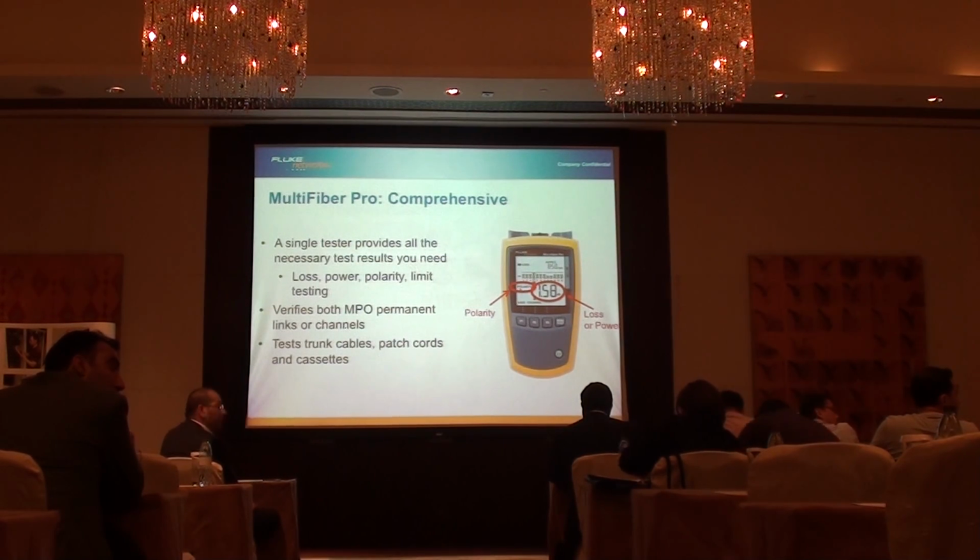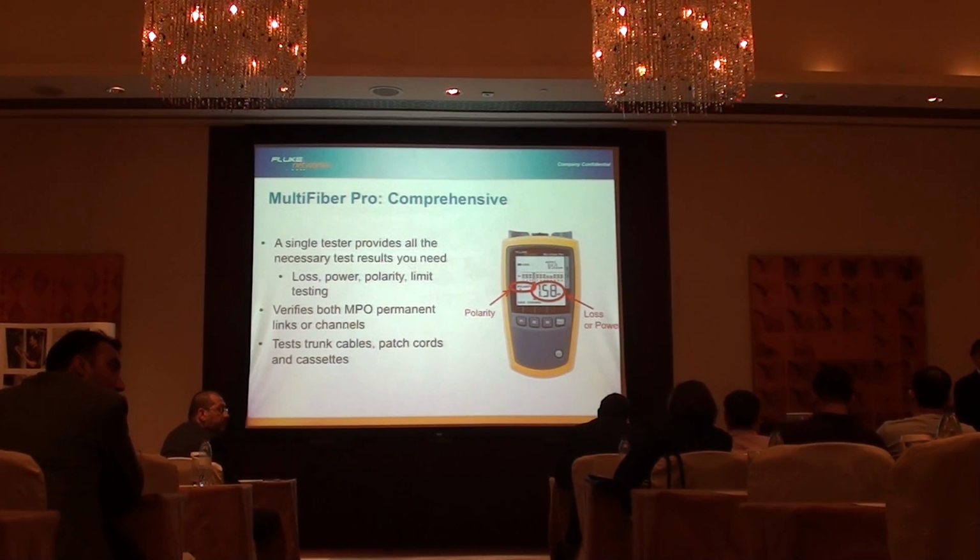And many of the time it might end up that it's the problem of the cable because the installation went wrong and they damaged the cable. So this tester can verify the cable if it's working well or not. Then if the cable is good, then you start doing problem isolation that might be this cassette or that cassette might have a problem and you continue.